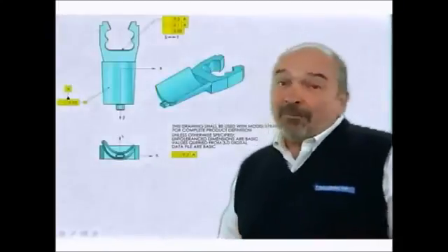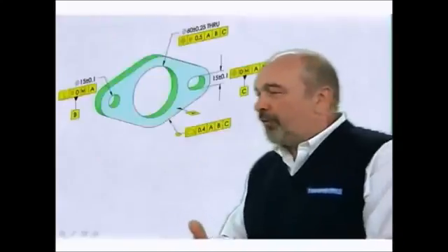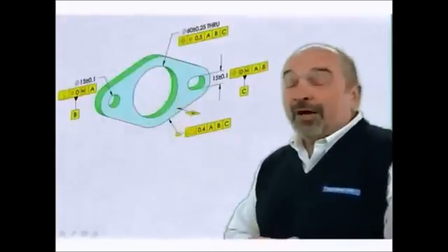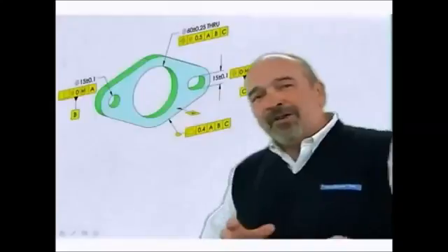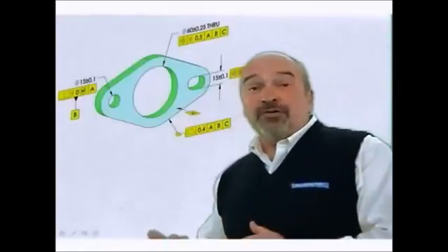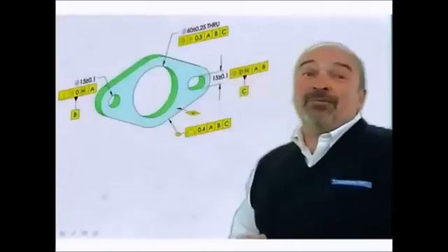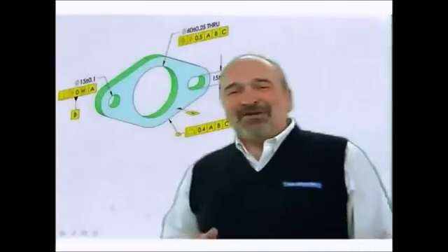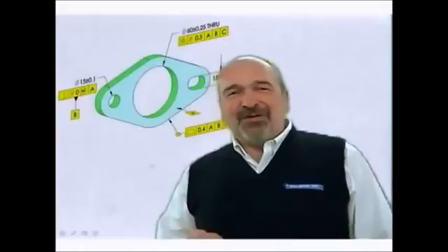They've expanded the composite tolerancing in position and profile. Here we're seeing several tiered composite profile. And my favorite, the Y14.5 standard ties in with the Y14.41 standard, which allows us to embed our geometric tolerances in our 3D model. You know, there's so much to cover in a tip.